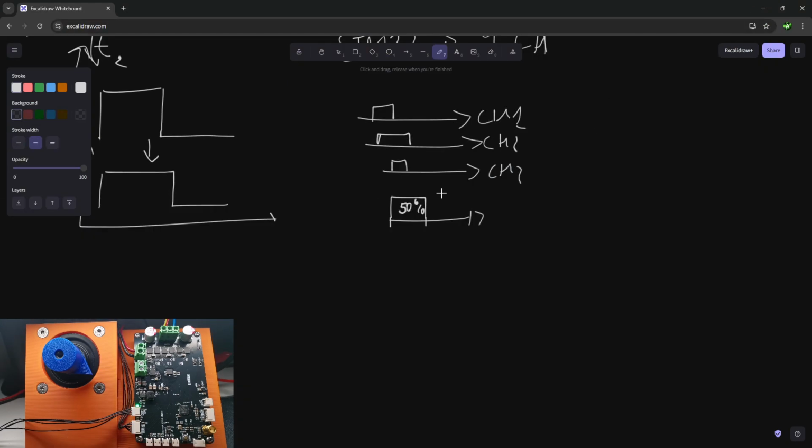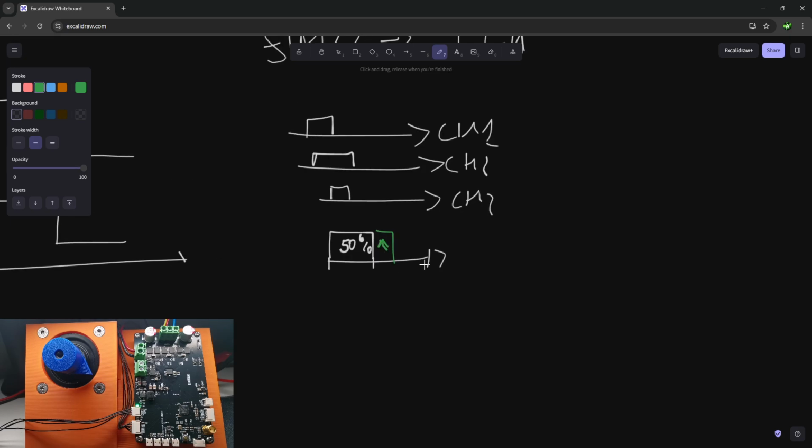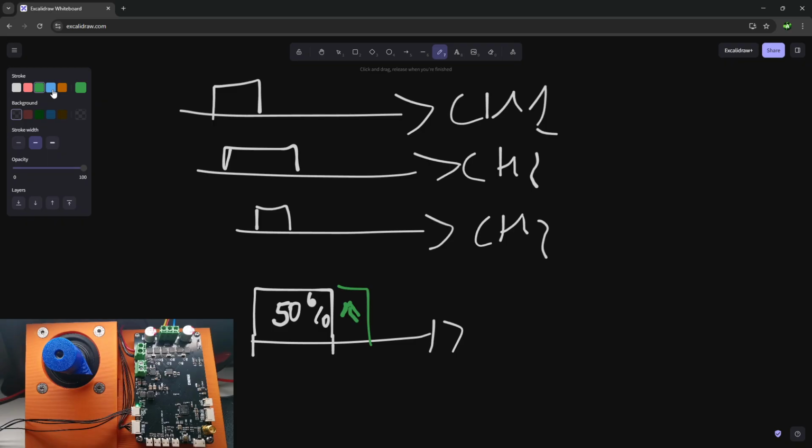And why do we do this? It is still the free time here. It's free. F, to pay respect. So when the measurement ends, when the encoder data is received, we have another interrupt. And this interrupt already handles speed calculation, position calculation, everything else. And the point is that we know this time for sure, it is known. We can calculate it. And we control this.